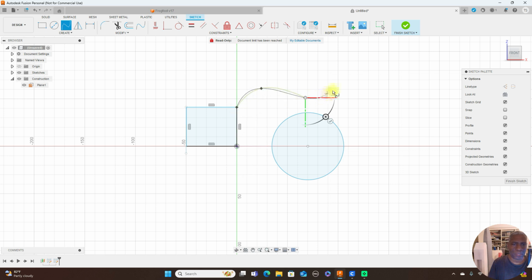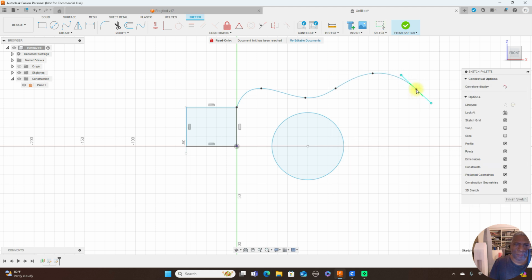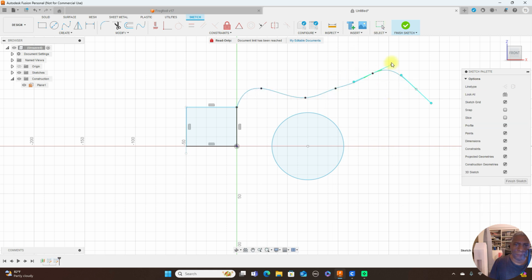And you want to use as few points as possible when you're modeling a part. Okay, and now you have these here, and now you can adjust the line itself with these, and you can move it with this here, and you can adjust all the points here again like that. So that's another command or tool that you'll use a lot, especially the sketch.